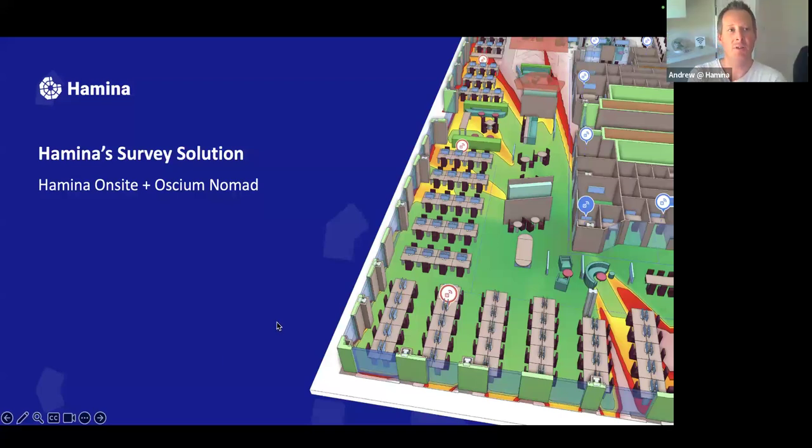Yeah, in fact, to add on to that, something that I used to do a lot when I was surveying. And I guess this is more, am I trying to find the problem and fix them, or am I trying to produce some fancy numbers to give the customer to say, pay me, everything's okay? But I would get two devices, one that could stream audio and the other could receive it, that were peer to peer. So it wasn't streaming via YouTube, which is buffered, or Netflix or anything. It was two devices on site, one transmitting audio over the Wi-Fi, the other receiving it. And I would just listen to audio the whole way around.